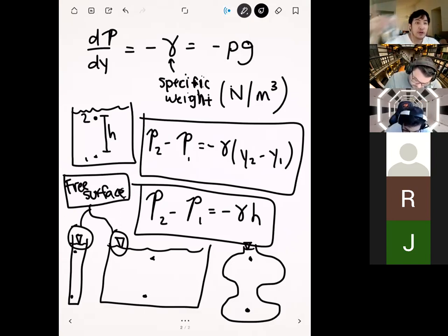If you look at a typical glass of water that I have right here, the surface of the water is right here. This would be a free surface because it's connected to the atmospheric air around us, right? This is a really important point for calculations because usually what we assume for these hydrostatic calculations is that any surface that's free, connected to the atmosphere, has zero pressure, okay?